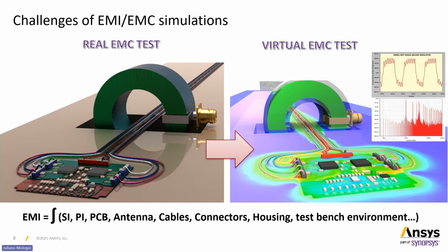For signal integrity analysis, you can create a cutout around critical nets in your PCB and simulate this. But take a look at this, right? For EMC, usually you have to simulate your design under test, which is your full PCB with 3D components like connectors, and then you have cables. In this case, we have a bulk current injection probe. So it can be really complex.